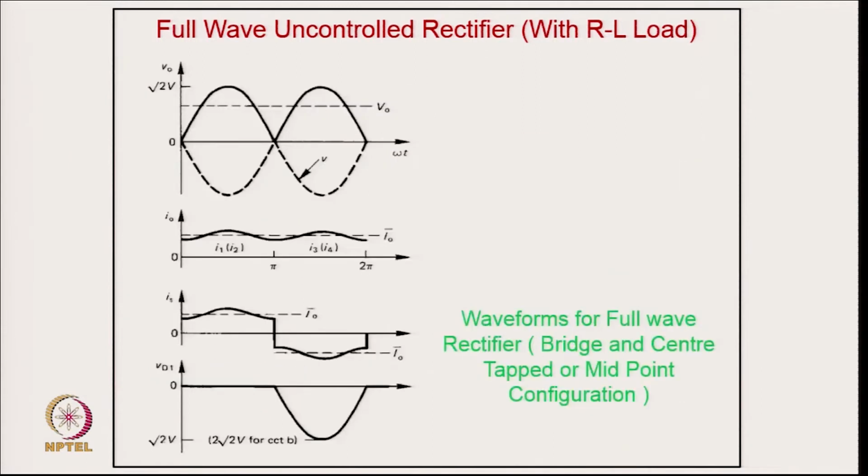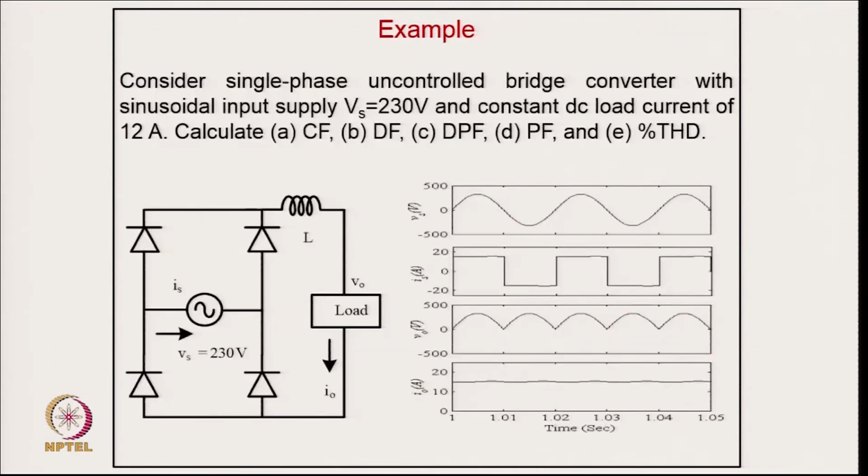But if you have a highly inductive load, then you will draw a square wave current from the supply, where the output current is of this nature. You can clearly see that this has substantial harmonics, ideally a THD of 48%, with the third harmonic at one third of the fundamental and the fifth at one fifth or so.